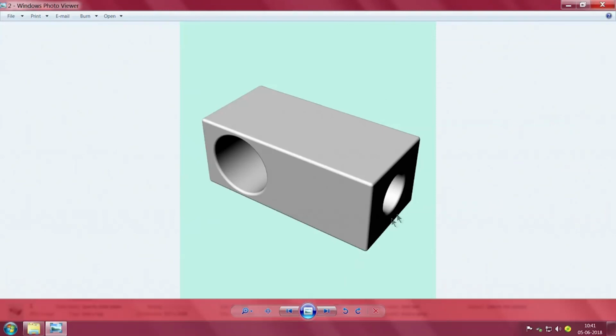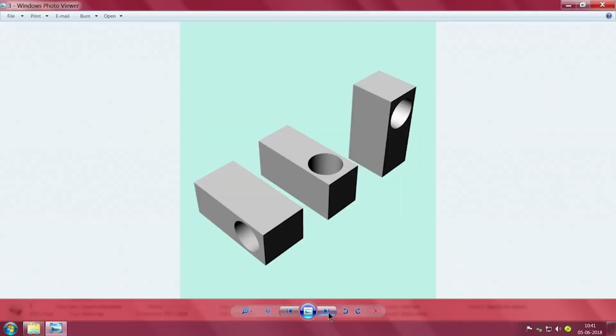Now if I keep it flat and try to build, the software checks first, and then a little bit of build material or support material is built here. Same thing here, support material is accumulated. So I have rotated it 90 degrees along this axis, and you see what will happen. Now the proper way is probably to build it in this direction. Looks okay, no? But again we have a problem. While we have solved the problem with the bottom bore, this filling up is required. So is there a way of getting over it?